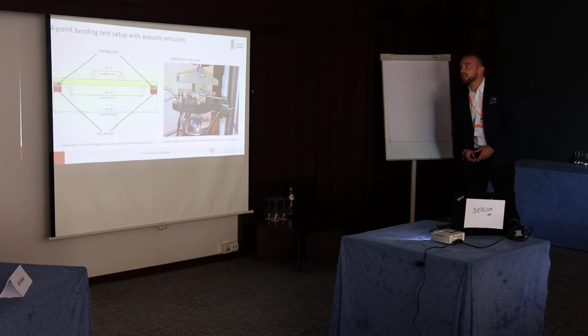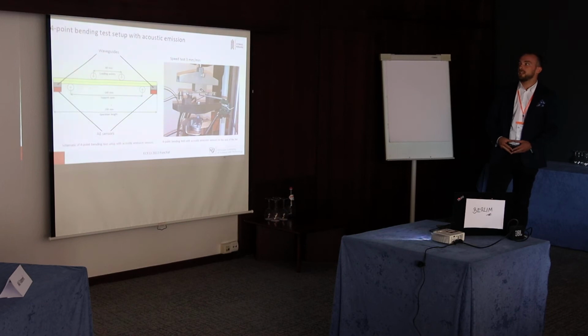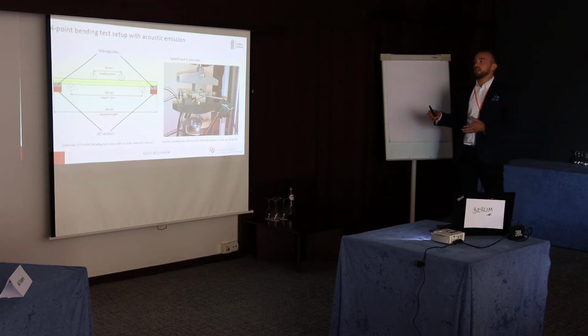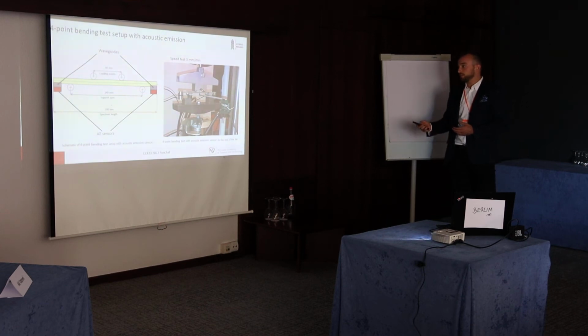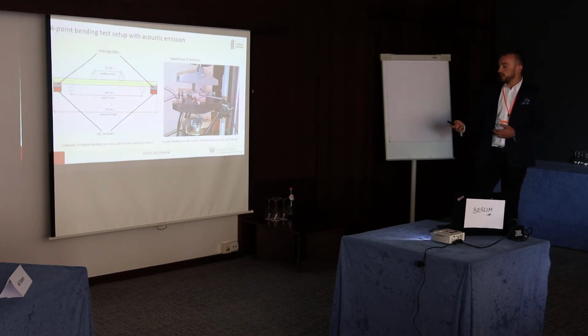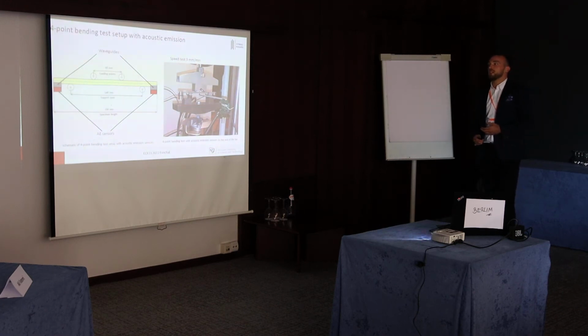The next experiment is a 4-point bending test, and in this experiment we try to correlate the amplitude and the frequency of the events to detect the breaking of the specimen. Here are the acoustic emission sensors, and this is the experimental setup in our laboratory.